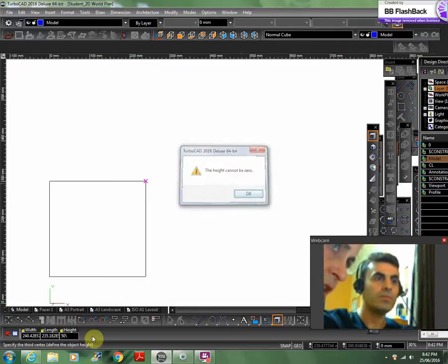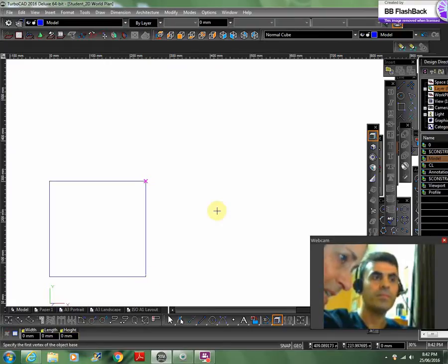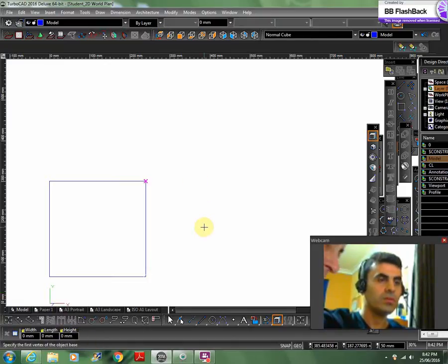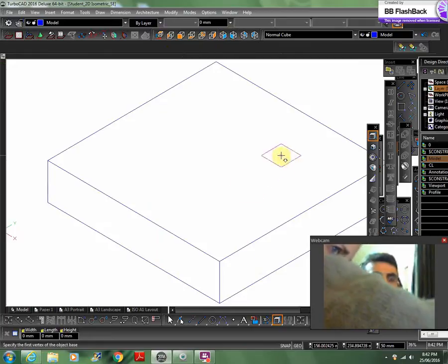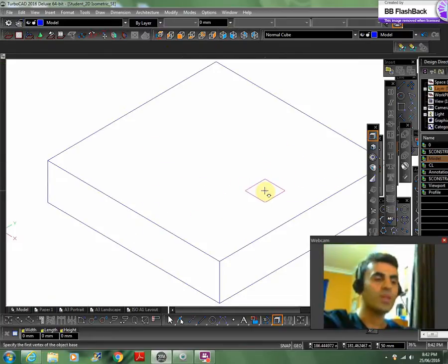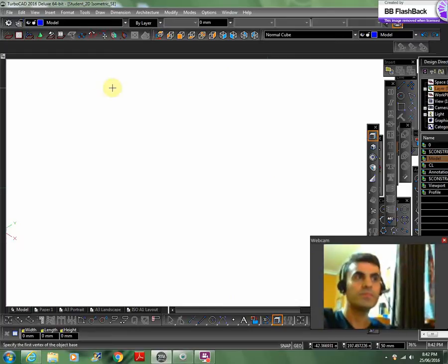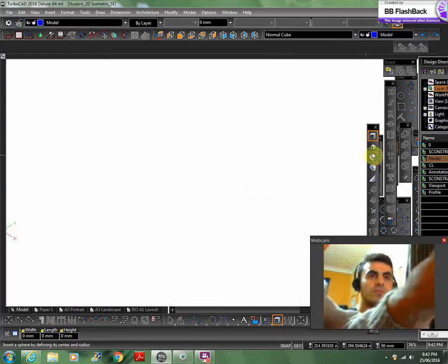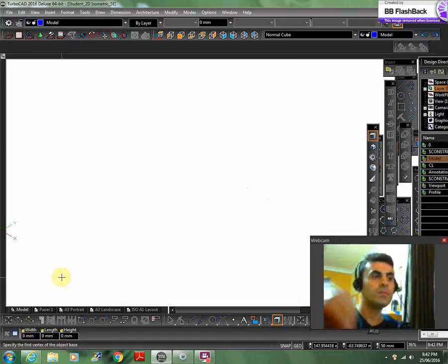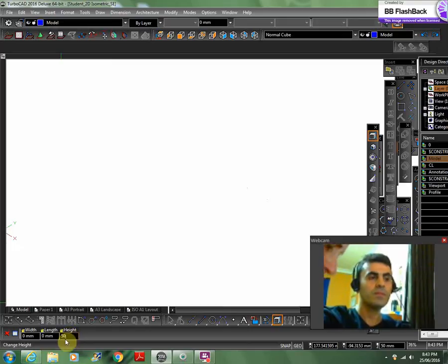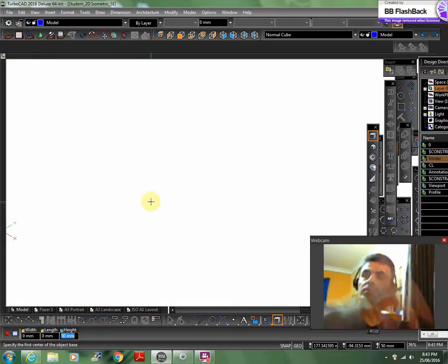The height cannot be 0. It's 50 millimeter. You did 0 millimeter, and you didn't lock it. Let me see. You have the inspector bar, right? 50. No, this is the one. I just use this box as an aid. Can you delete it again? Just go to edit. Can you go and choose the box again, and then click the by height 50? Millimeter 50 has to be there, and then lock it. And these two, you say you don't need to put all the dimensions. Yes, exactly. Okay. Draw your box.